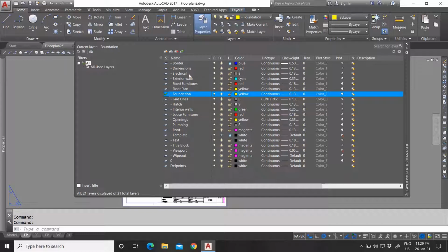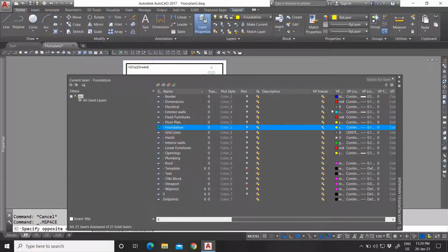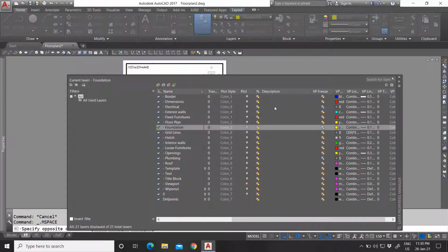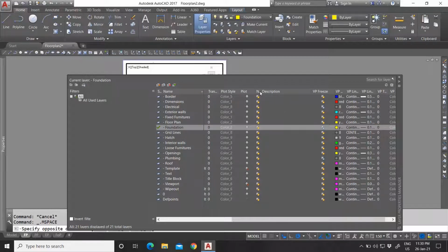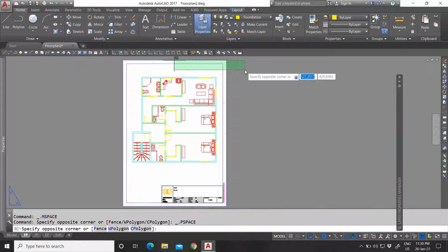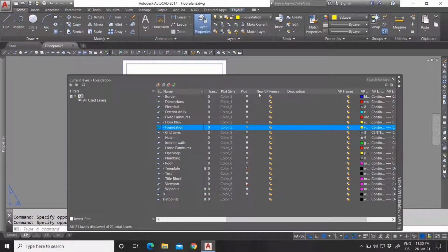It is set to, first of all, of course, you have to go into a viewport to be able to see it on the list. So right here we can see which viewports of which layers are frozen in this specific viewport. Now this right here is, let's see, I want to just make this bigger. Why is it not, well, another command is active. Oh, sorry, I have to exit that command, of course. Right here we can make this bigger, and this will freeze the new layer.